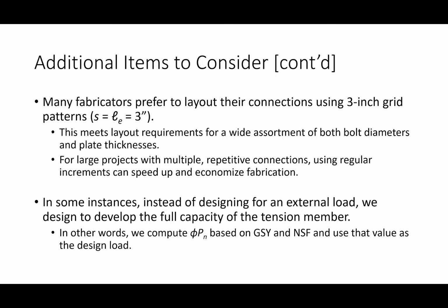We've got some senior design teams working on some connections, and if you asked me, without any context, any loads, anything, to just rough out a connection, I'd probably say, why don't you try out a 3-inch spacing just to get started, and we can tweak it later. It's sort of my go-to without any science to it.